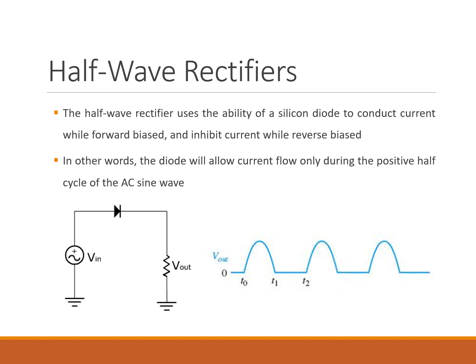Looking at the circuit, if we look at the circuit like an overview, you've got an AC source, which is your voltage in. You have a single diode, it's in series, and a load resistor, which is what the diode's in series with, where the output voltage is going to appear. And the result is that every other half cycle of AC gets clipped.